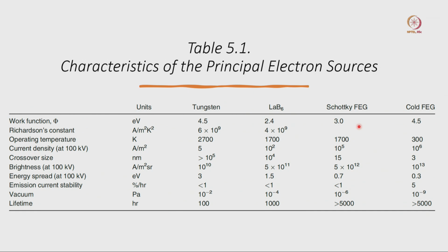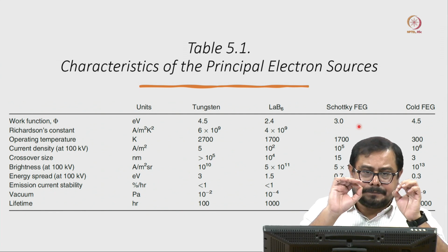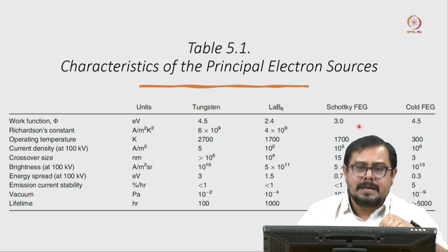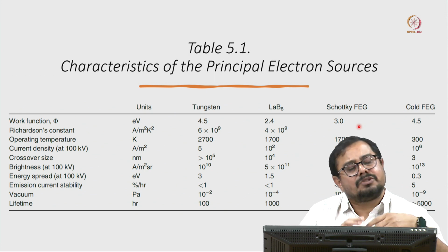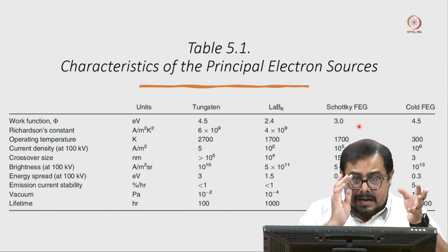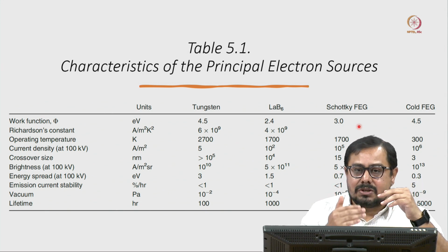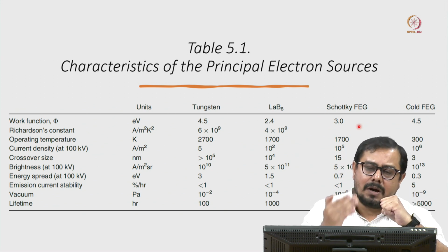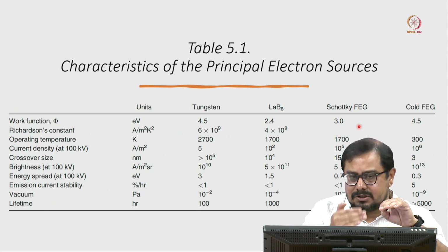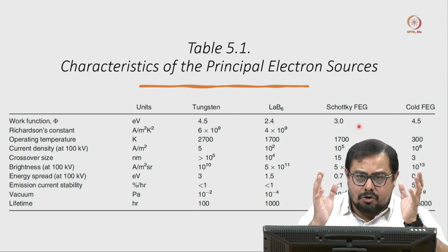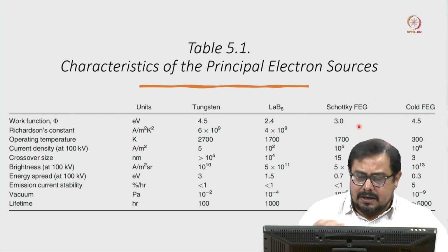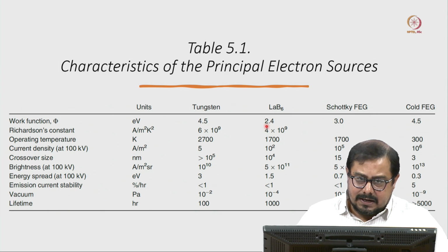So if we consider this normal tungsten metal, they make a groove where the zirconium hydride powder will be, and then we use very high heat energy, something like 1800 Kelvin, and it gives a chance to oxidize, which will coat the outer surface of the filament, and it will be zirconium oxide. When it is coated with zirconium oxide, the work function is drastically reduced,